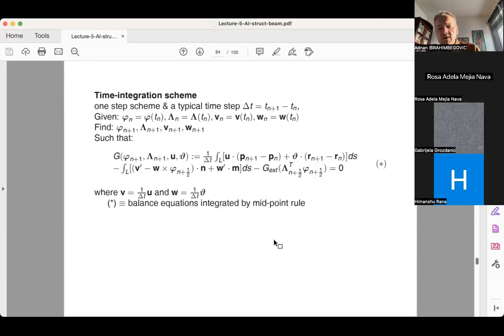So if I want now to do this entire integration scheme, basically I'm doing a one-step scheme. We talked about these two basic schemes, which is the implicit and explicit Newton type of Newmark's type of method. The implicit was a trapezoidal rule with its coefficients beta 1/4 and gamma 1/2. And central difference was explicit with the gamma again equal 1/2 to be second order scheme, but beta equal to 0. So whichever is the version I'm using, I'm now discretizing everything from Tn to Tn plus 1.